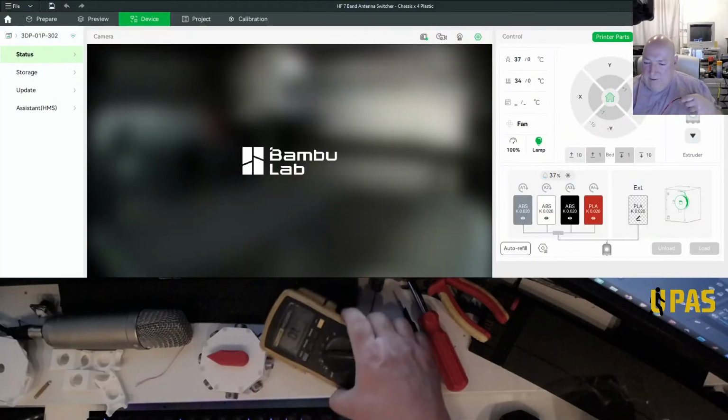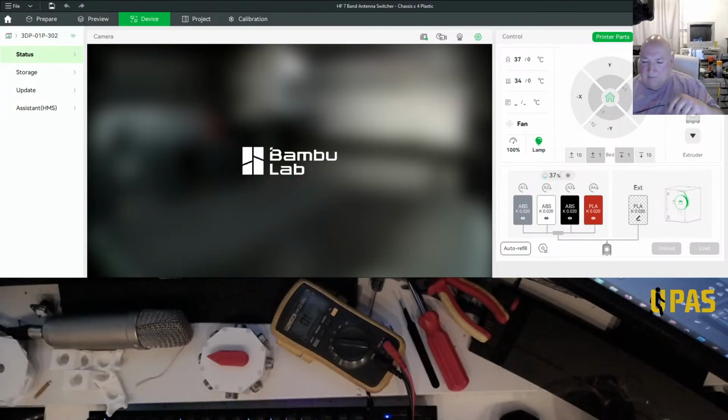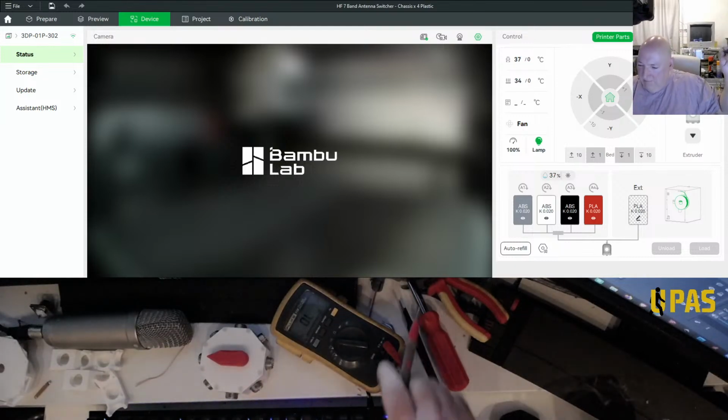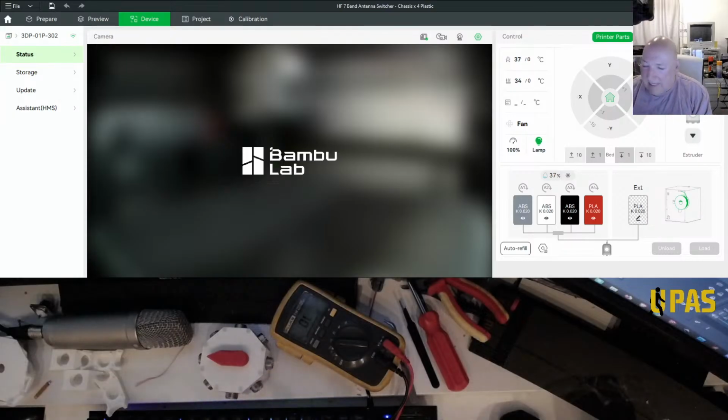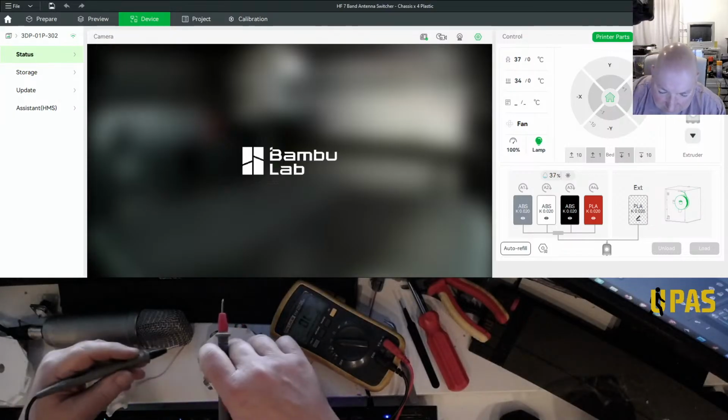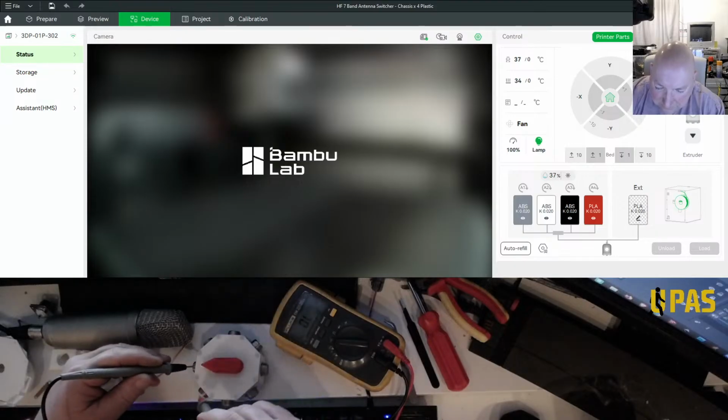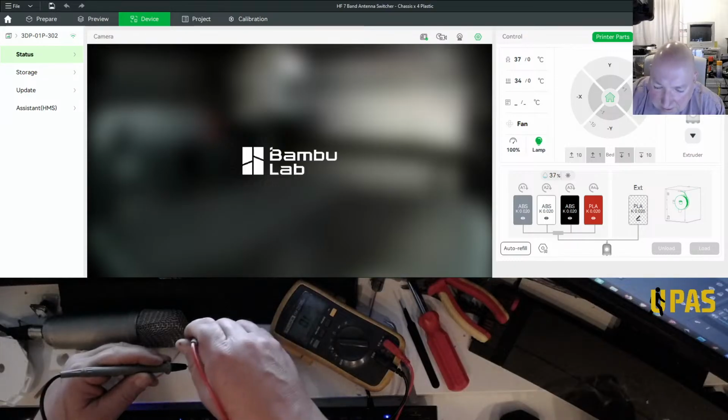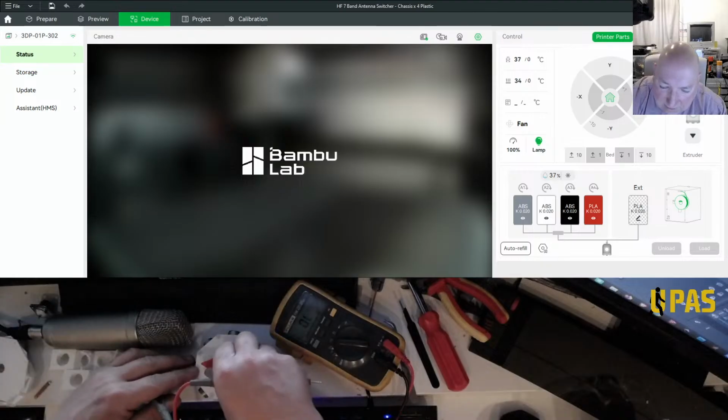Get it tested. Put the meter on it. Yeah, I don't know. Right, let's put the drop down view again. Put the meter on it. So we've got ohms, just basic ohms at the minute. Of course, the cables are all twisted again. Why doesn't someone invent some probe cables or some leads off a multimeter that doesn't get tangled. Right, let's see what we got. Let's first make sure we got frame ground. We've got frame ground, so your incomer's there.